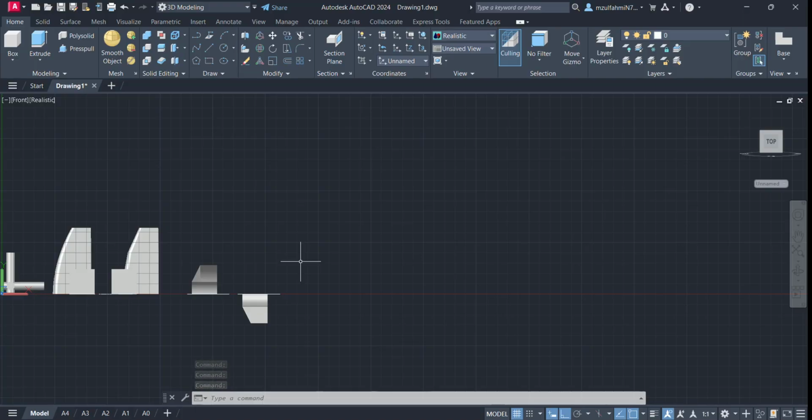So what I want to do is create, okay, you can also create a polyline, PL, enter. PL is the same as line, but it will continue as a line. So for example, I create 350, 300, 400, 430. So this is the first one.